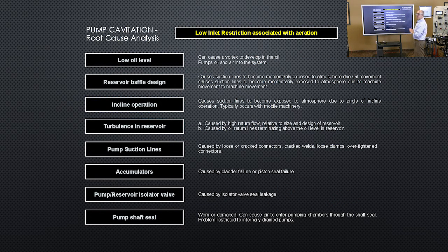Causes of pseudo-cavitation are a number. Number one is a low oil level. If we neglect oil levels, of course we're going to let air go into the intake of our pumps. Next is reservoir baffle design. If the machine is moving and you're momentarily taking in air, it's going to cause cavitation or pseudo-cavitation.